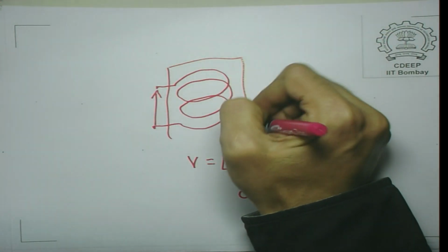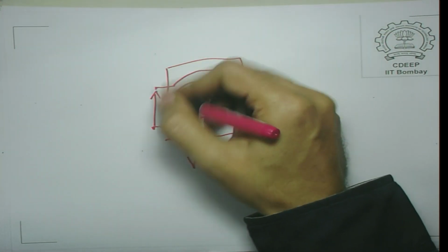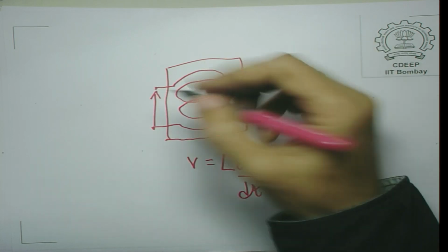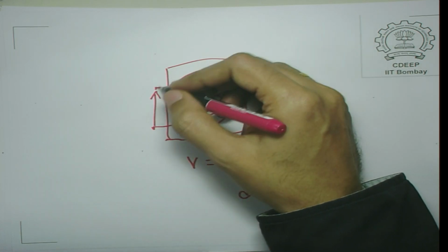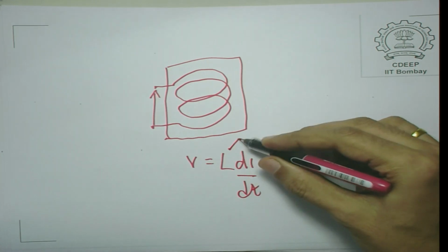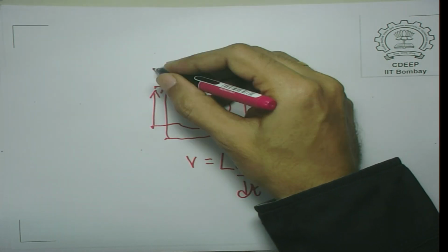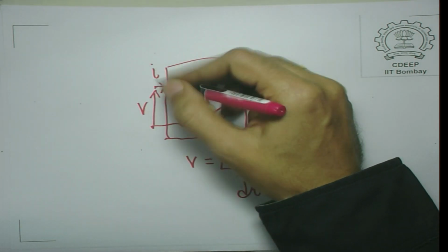When you compute the flux and apply the right hand convention consistently and correctly, you will find that if this is the region where the inductor is and there is hardly any magnetic flux here, so we can define a potential difference here, then this L turns out to be positive if voltage is defined in this way.